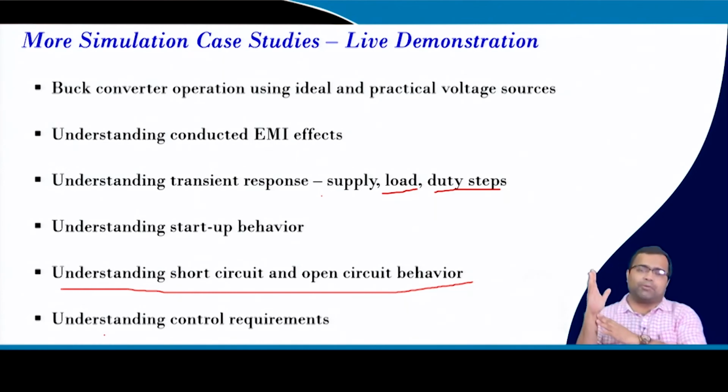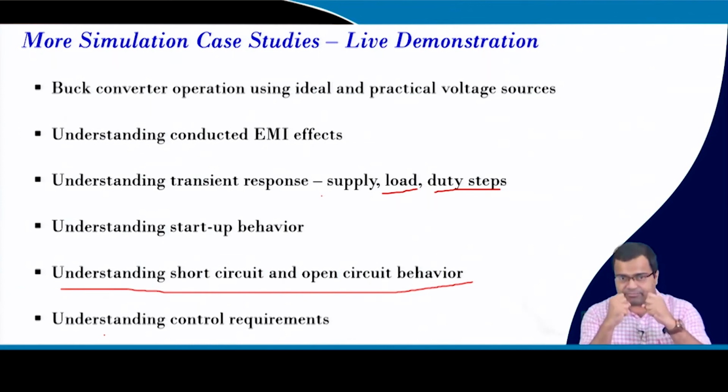From there it is very clear that supply disturbance can severely affect the performance of the converter and it can introduce a lot of oscillation. If you connect many power supplies to a single source and one of the power supplies injects such behavior, and your source is not properly regulated, then it may propagate to the other converters and it can create severe problems for the interconnected converters.